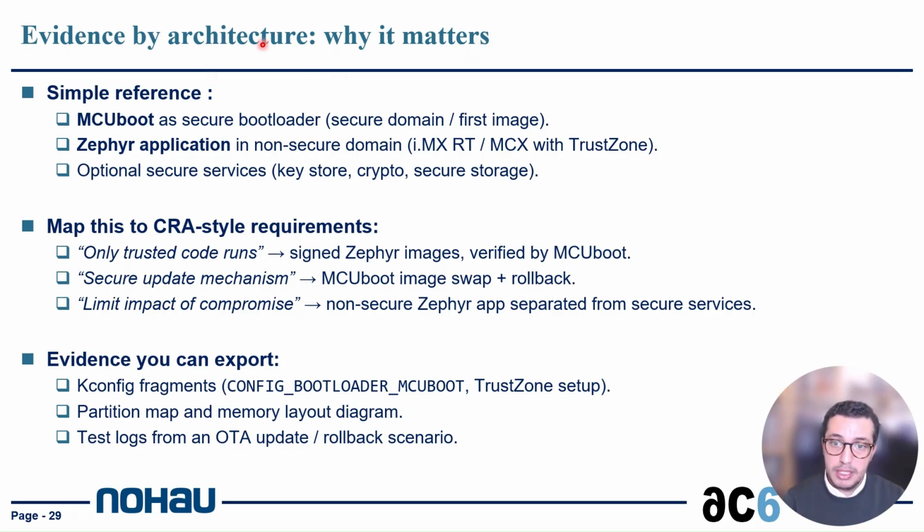So we can show evidence by architecture. As we explained, why it matters: I used just a simple reference design. In my example, I was using MCUboot as the secure bootloader. So we can have a secure domain and we can implement that. It is part of the Zephyr application. The Zephyr application will run in the non-secure domain, and optional TF-M secure services we can use for secure storage and for secure update.